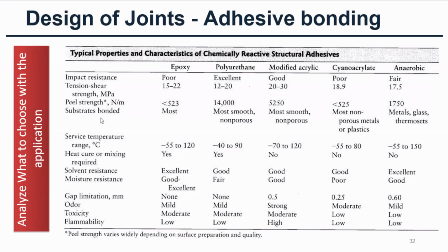Service temperature range is minus 55 Celsius to 120 Celsius. Then heat cure, mixing requirements, solvent resistance. Solvent resistance is excellent in epoxy.